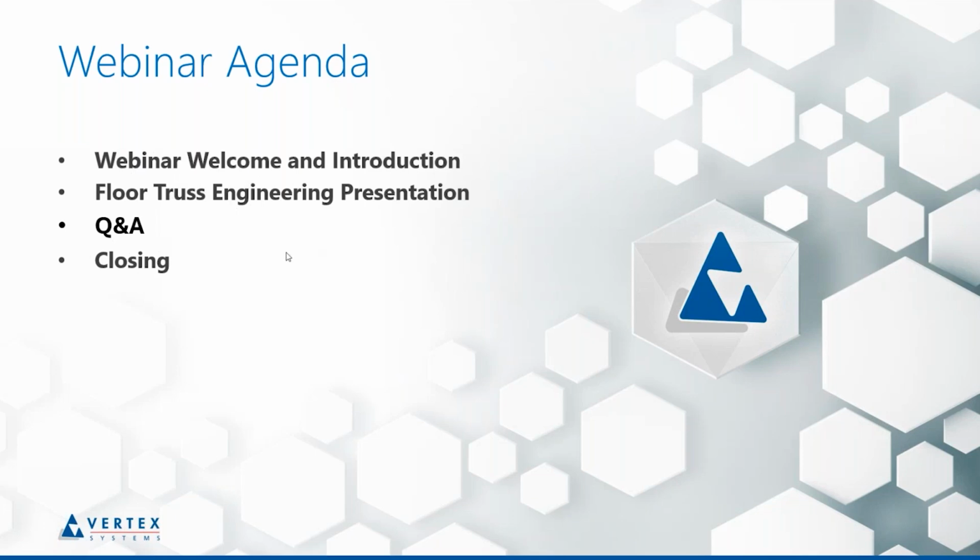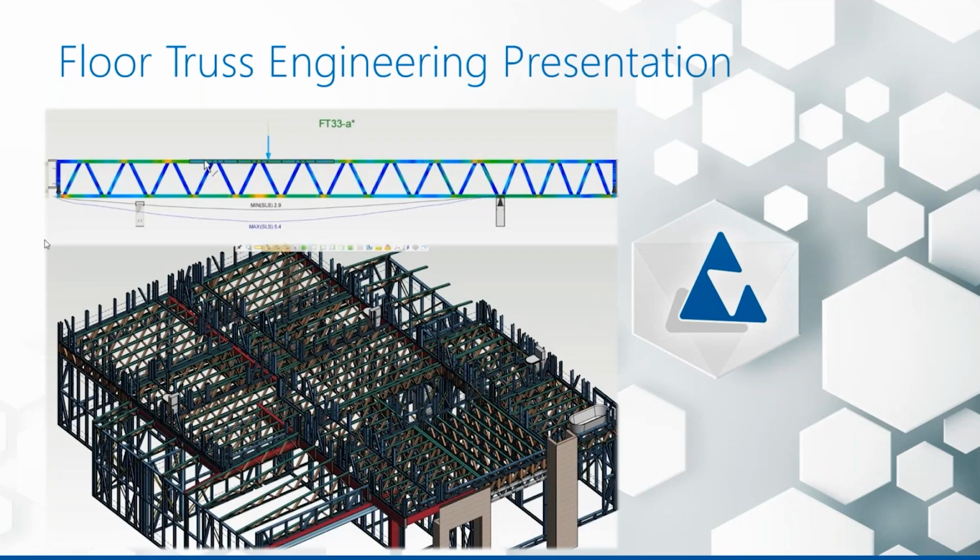Okay, thank you, Jukka. Floor trusses, some people also call them webbed floors, are one of the most common floor systems in light gauge steel constructions. In fact, I think they are probably the most common one. They come with a lot of benefits. They are very flexible, so you can design different floor depths. You can even make them from the same profiles you use for wall frames, which means you don't need to buy another machine just for your floor system. And because of the open web design, plumbers and electricians can run pipes and cables through easily without drilling